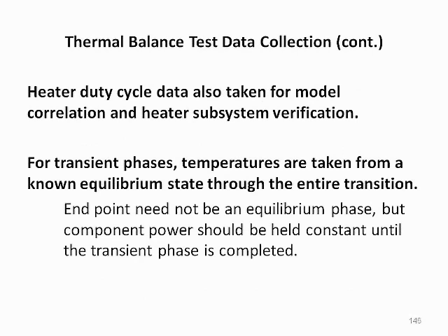Heater duty cycle data is also taken for math model correlation and heater subsystem verification. During transient phases, temperatures are taken starting from a known equilibrium state and then through the entire transition. The endpoint of a transient phase need not be an equilibrium phase, but spacecraft component power should be held constant until the transient phase is completed for all components.